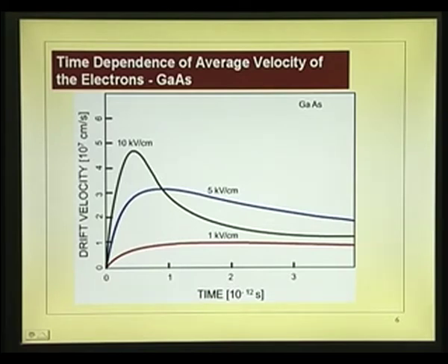So, you can see now, if the electrons are launched into a channel where the fields are high, they will experience velocities which are in excess of the saturation velocity. Ultimately, you may have saturation velocity, but during this period, it goes through that. Okay. Now, let us see what will happen with distance. After all, with time, the electron gets accelerated with high velocities, and when it gets accelerated, it moves also. At the end of 1 picosecond, it would have moved through some distance.